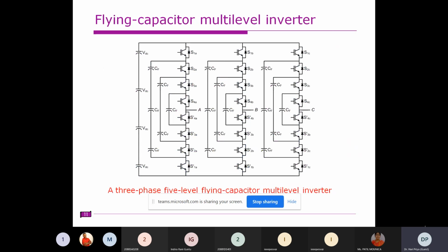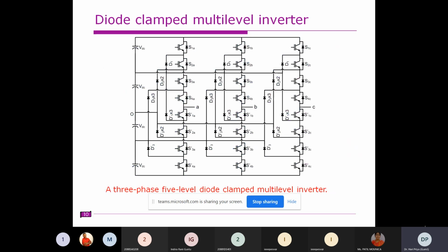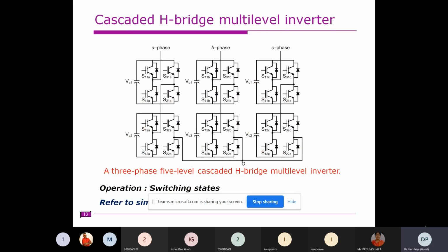For example, these are the popular multi-level inverters, but to make you understand how this is going to affect the DC voltage, let me tell you. For example, I want my output AC voltage of 200 volts, whatever it is, let me assume peak also. Okay, some 200 volts output voltage I got. So each DC voltage I have taken as 100.